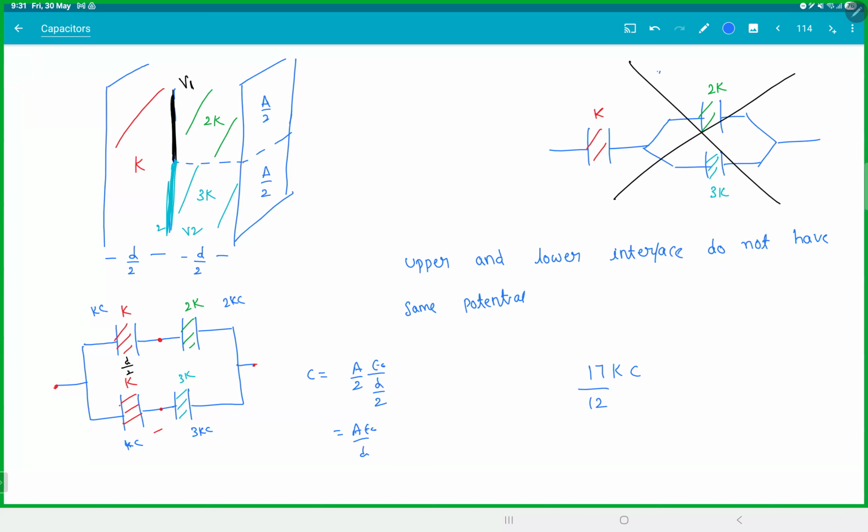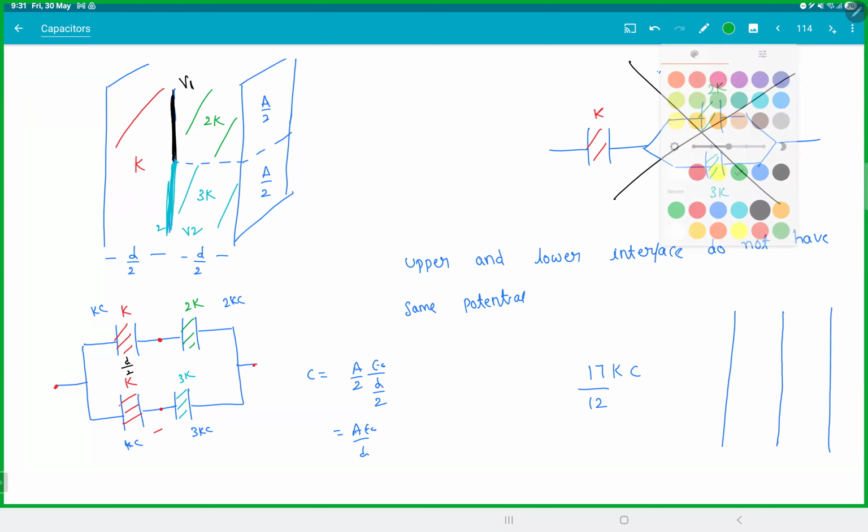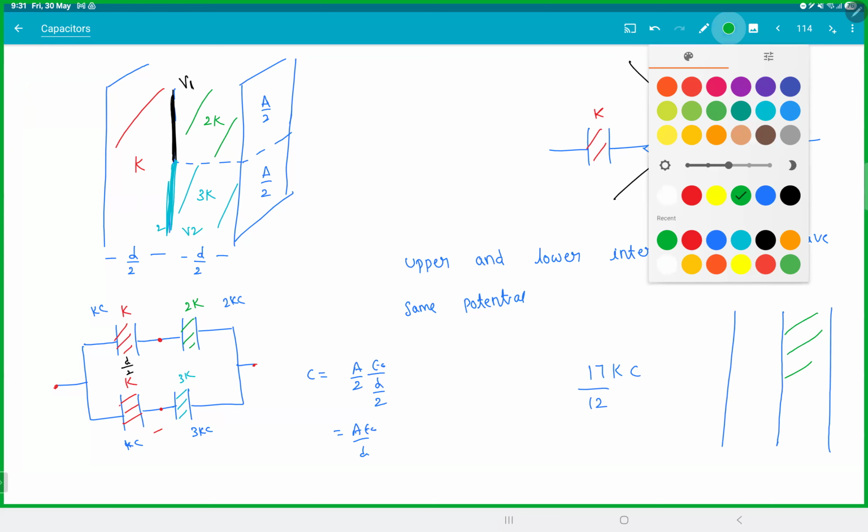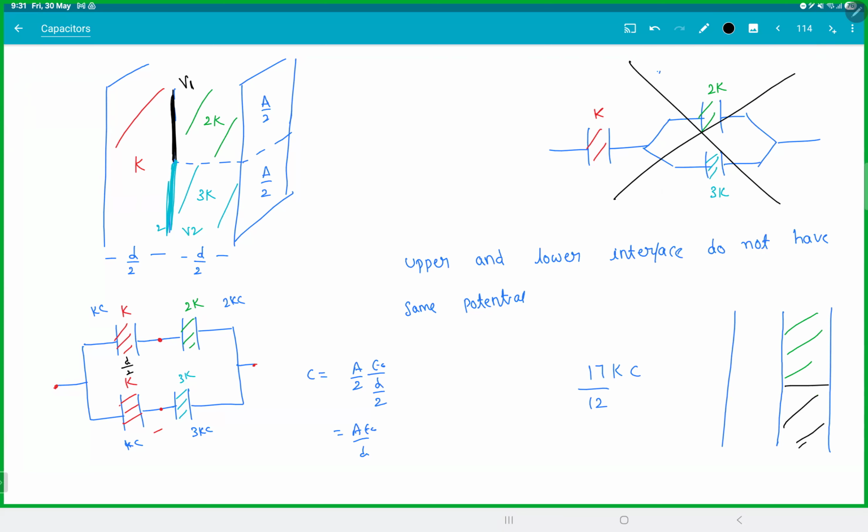Pretty good one. We encountered the same thing in heat transfer. So you know how to make them parallel? If you want to make them parallel, then you put 3 plates. You put a plate in the middle, and fill up the space with a dielectric here and a dielectric here. Now, because it's a metal plate in the middle, the potential becomes the same. Now they're in parallel.